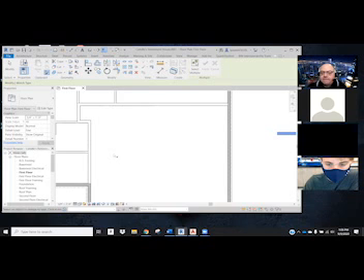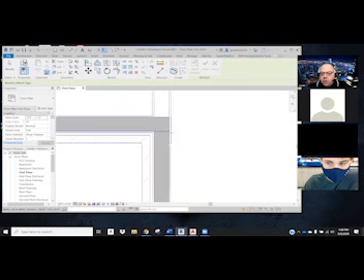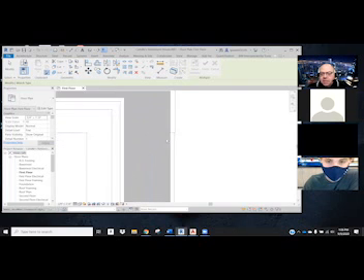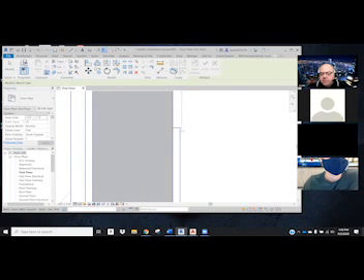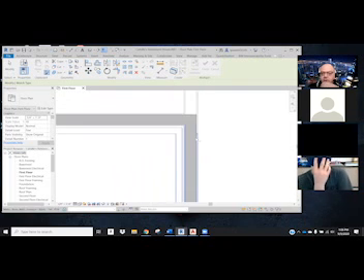Just that quick. And then you might have to go in and use your Align tool to get them in the right spot so everything's flush. Notice your walls should all be nice and flush, and this wall is a little thicker because of the gypsum board, but we're gonna be okay with that because that's the code requirement.